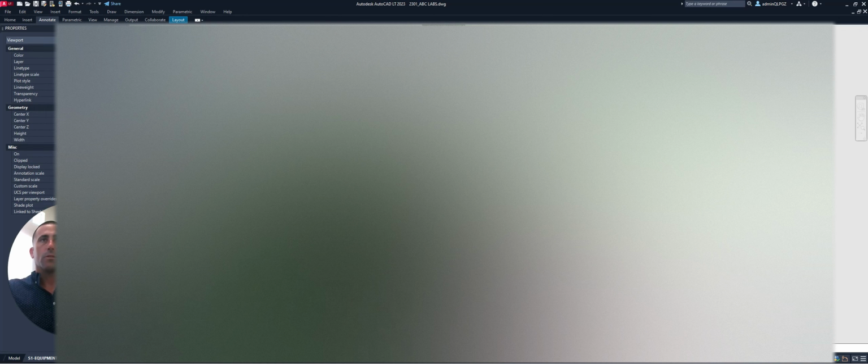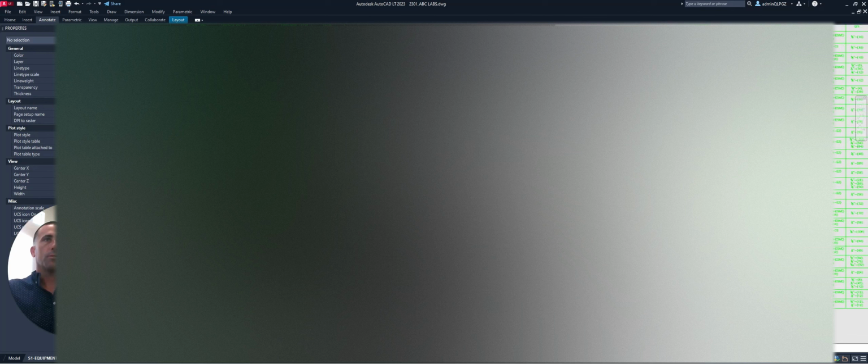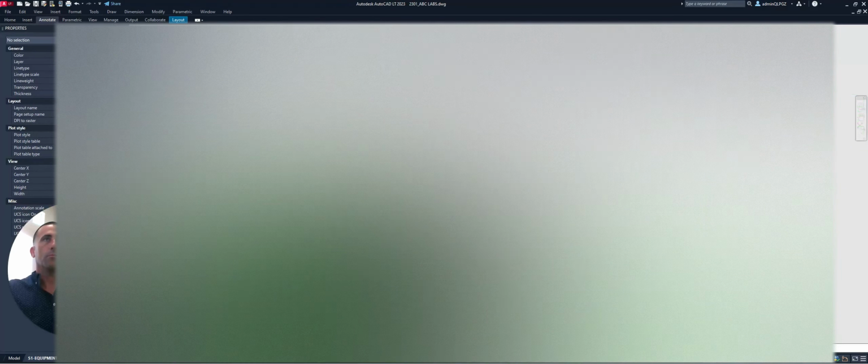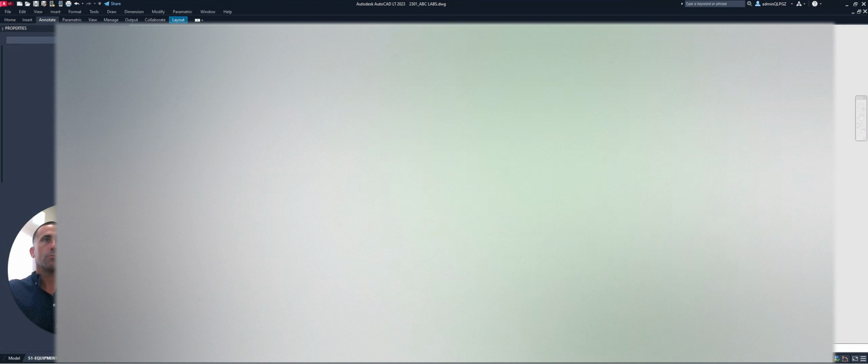And if I want to, I could extend this out. I'm really not concerned about cutting off this text, because that text is going to appear in the architectural sheets. So really the sheet only needs to pertain to just what information is needed for the contractor to build the foundation slab work. So we're going to start with this. We have our dimensions right here, 13 feet 9, 6 feet. So I don't need to duplicate those. I don't need to put any dimensions. If I didn't have those, I could throw some dimensions on there, but I'm not going to duplicate it.